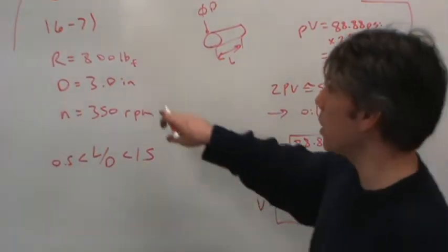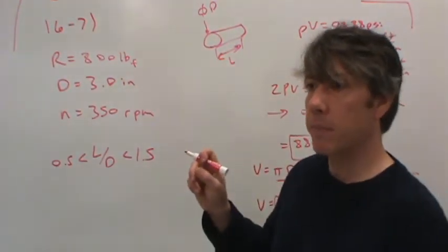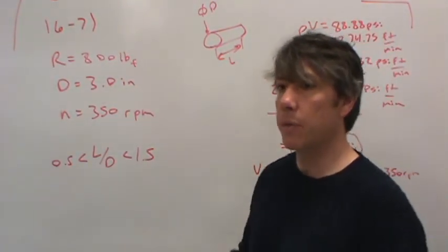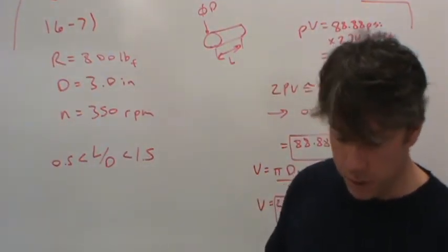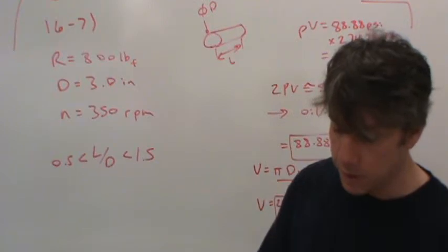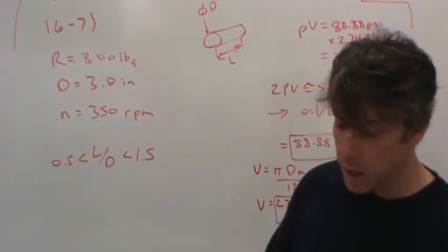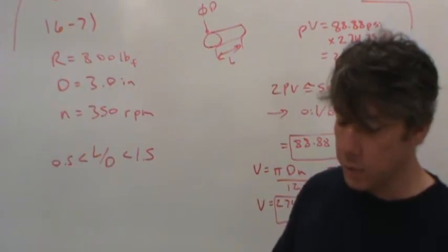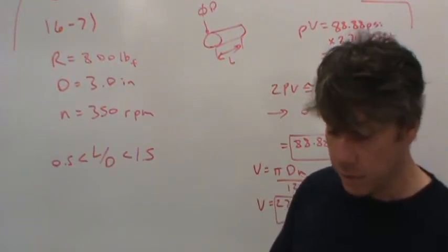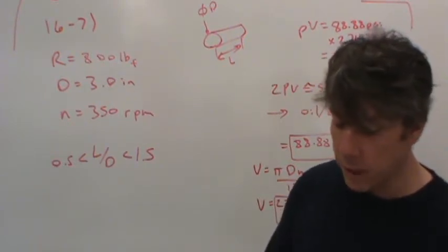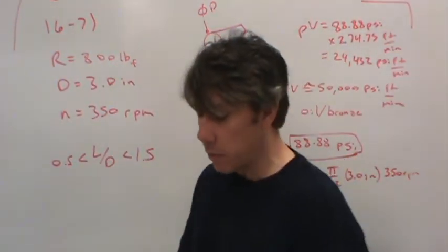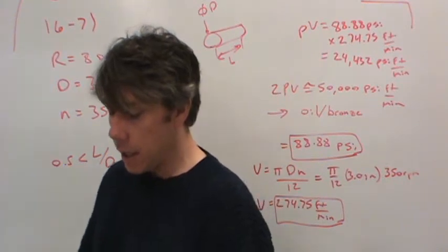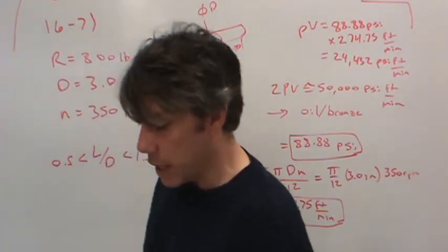Okay, so you will have some clearance. Notice that the 3-inch diameter is a nominal diameter. The actual diameter of the bearing and the journal will be different. Nominal diametral clearance has many factors affecting the final specification of clearance, such as the need for precision, thermal expansion of all parts of the bearing system, other variations, shaft deflection expected, means of providing lubricant, and manufacturing capability. One long used rule of thumb is to provide 1/1000th inch of clearance per inch of journal diameter.